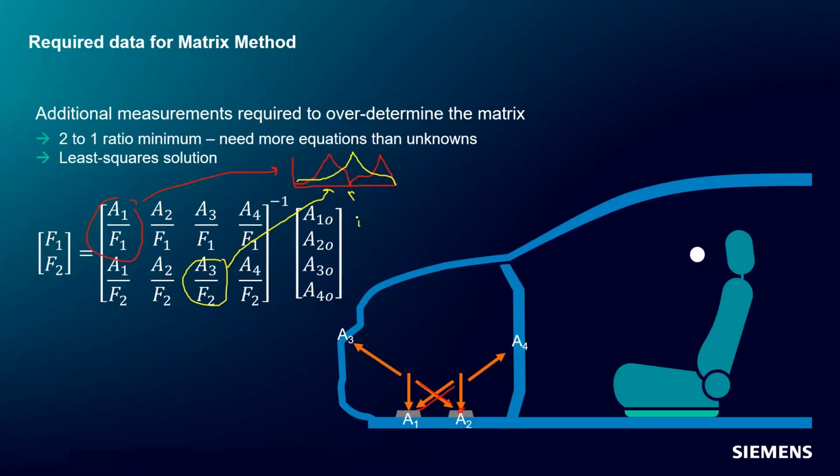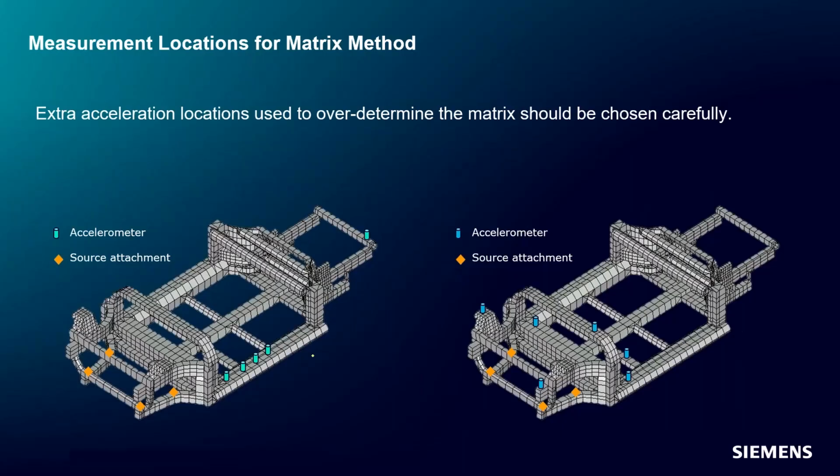And what will happen is if we take all the FRFs at once and do the inversion times the operational accelerations, we hope that it doesn't go to 0 and that we can get a good, reliable estimate of forces. And you can see here, these orange dots represent where we want to calculate the forces.